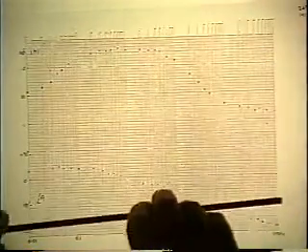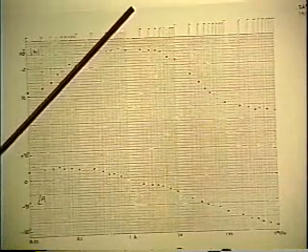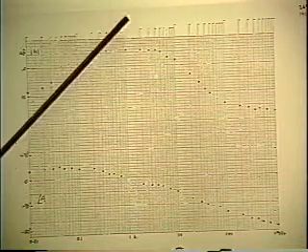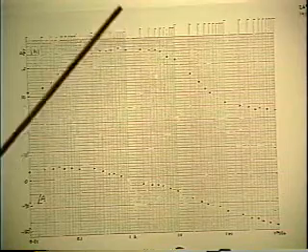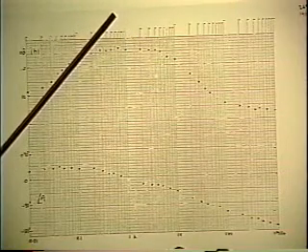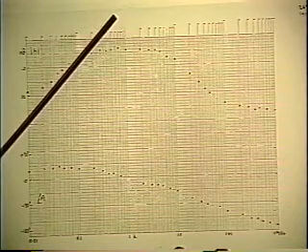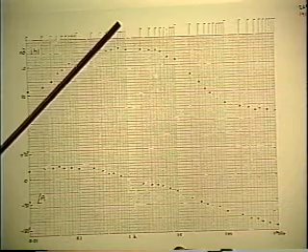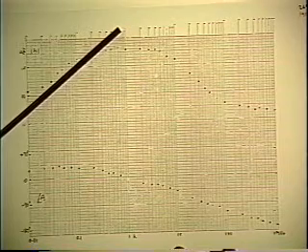Then you do the same thing going in one direction or the other. If we go in the low frequency direction, obviously there is a single slope in here, plus 20 dB per decade slope. So you take a straight edge with the right slope and slide it around until you get the best fit over a limited frequency range down here. Now, it's important, of course, that you use the right slope, even though you could fit the points over a wider range by taking a shallower slope.